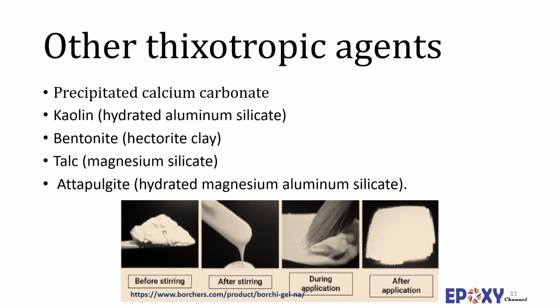Cibrico Corporation of Hawkins has recently introduced a new relatively inexpensive filler called Seal Cell, which is a micron-sized multi-wall hollow glass filler in size range of 1 to 115 micrometer. The particles have both spherical and irregular geometries, which is claimed to provide advantages in improving tensile strength as well.